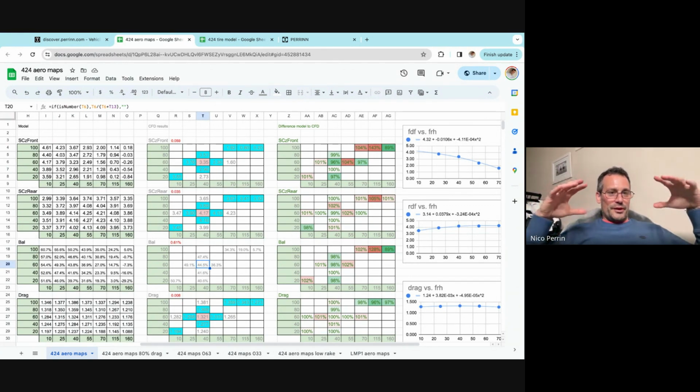And that's typical on a high performance race car. I always find that you need aerodynamic balance just under weight distribution. And the reason for that is as the car gains speed, obviously in a slow speed corner, what dominates the balance is your weight distribution. There's less aerodynamic load, so the vertical load on the tire is more dictated by the static load, so the weight distribution of the car.